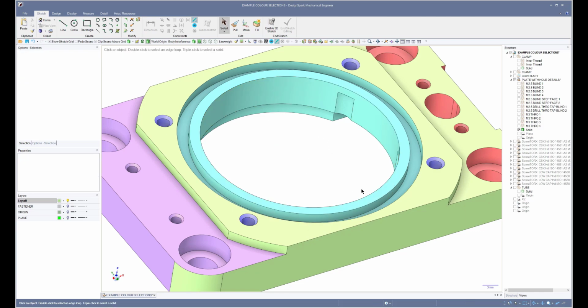And now I measure between these two curves. It will have a distance not of the offset, which was 2 millimeters, but now it has an offset of 1 micron. So that is something you have to be aware of. In this case, meaning although the axes of the holes are parallel, they are offset by 1 micron.